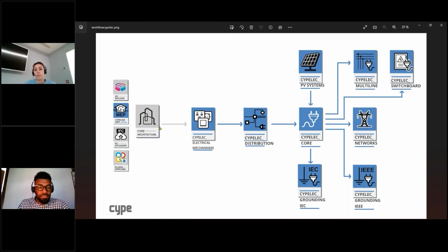I see. So if you have an IFC, you can work with other software. But if I only have a 2D file, how can we work with them? Yes, if for example your client sends you a 2D file and you're gonna have to generate the IFC building model. So in order to do so, you can use the IFC Builder, which is a software where you can generate the 3D IFC building model of your building with a few simple steps. So there's no limitation in it.